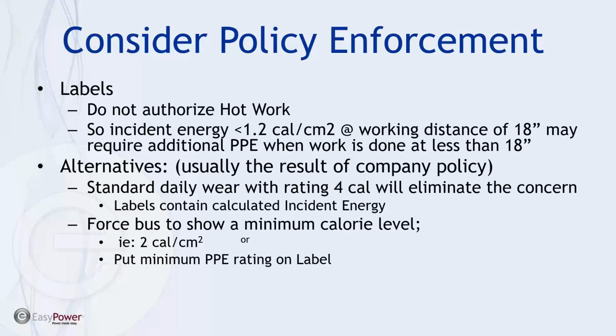Okay, so with all that in mind, the alternatives basically, in many cases, manufacturers just say, okay, we're going to establish a daily wear criteria for qualified workers with a rating of 4 calories per square centimeter, which will eliminate the concern. We're just going to label everything as the actual incident energy, and then only allow qualified workers to be in the area if that panel is going to be removed. And so this seems like a fairly reasonable thing to do.